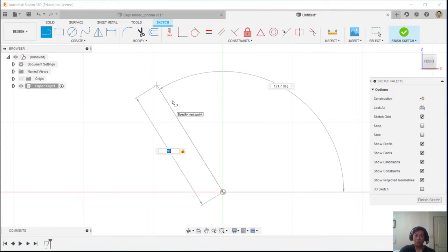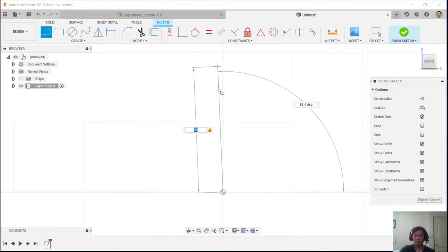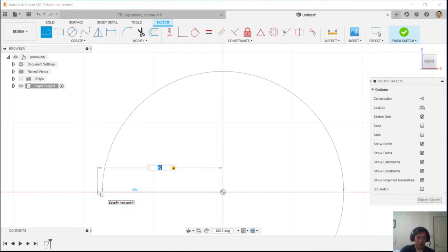But if you want to create it with an angle, as you can see, if I hover next to the vertical, it will have a vertical icon over there. So it's called a vertical constraint. A vertical constraint means that it puts the vertical constraint on the line, so the line is perfectly straight up. Okay, as you can see, if I go here, it's horizontal, so the line is perfectly horizontal. Okay, as you can see at the angle.